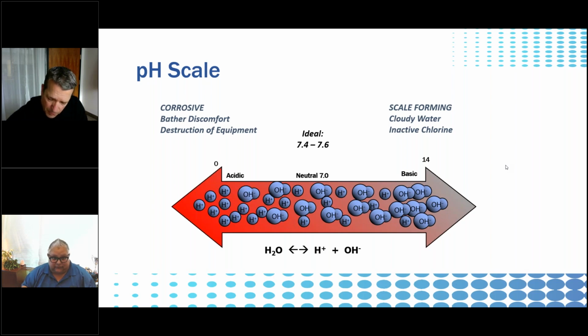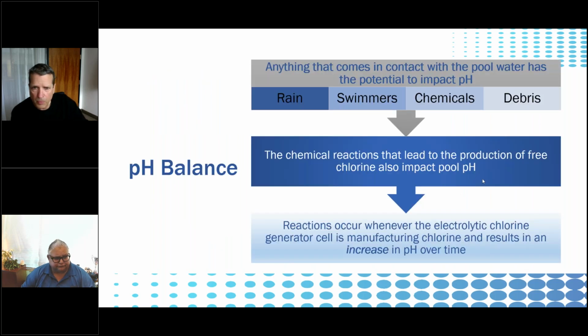So even if you're pumping out 10 parts per million of chlorine into the pool, which would be tough for a cell anyway, you're only able to utilize 0.9 parts per million of it at that point. So pH has a huge impact, and as it goes higher and higher, your chlorine gets less and less efficient. As it gets less efficient, you need to make more and more of it to try and compensate. So focusing in on balancing pH is an important part of maintaining a saltwater pool.